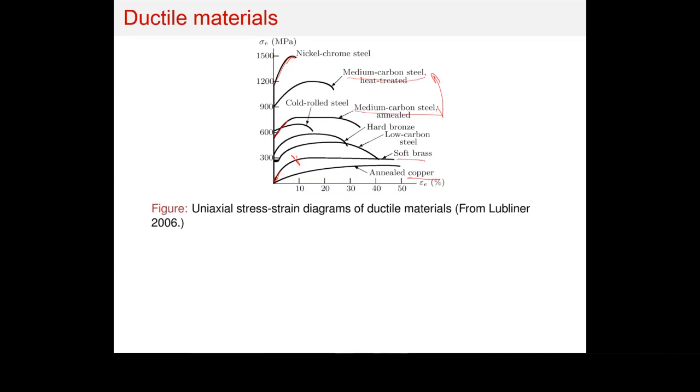Nonlinear doesn't always mean plastic. If you look into different types of polymers, they would certainly behave in a nonlinear way. For example, it is going to behave like this. And when you release the stresses from the polymer, it's going to restore all the way back to zero stresses and zero strains. So be careful about what you consider nonlinear and what you consider plastic.